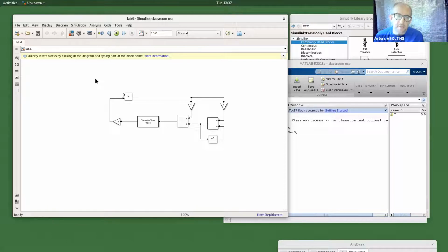Why is it needed, why can't we take this signal directly? This is because sometimes we need to generate a sinusoid, but the reference signal could be not sinusoidal, or it could be, for example, modulated. Or it's also possible to put some divider here. In this case, this PLL could generate n times higher frequencies than the reference.